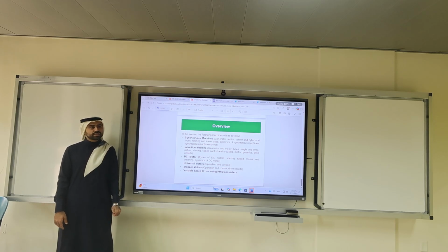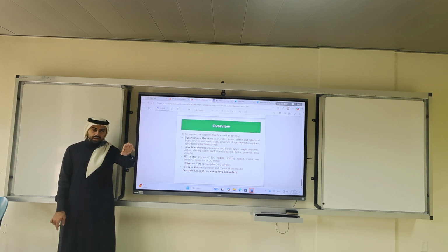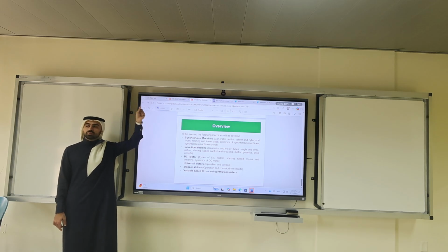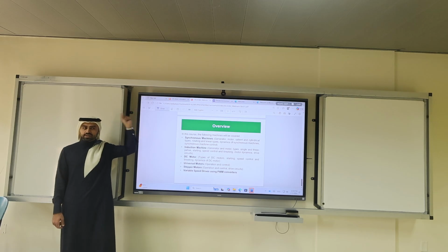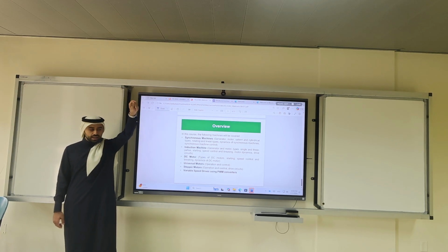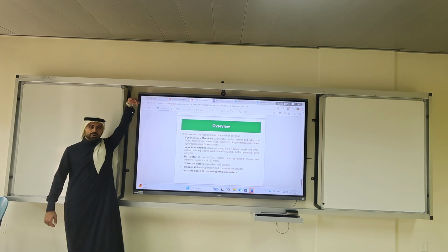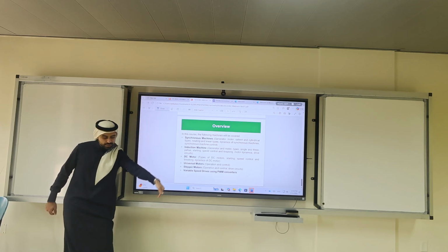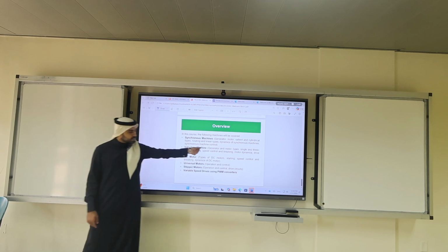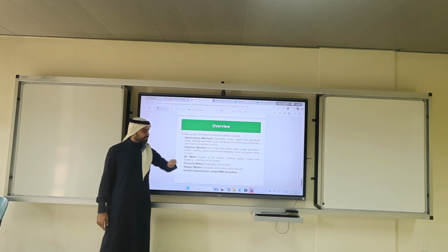Also, I remember from their discussion that the induction generator is directly connected and gives you variable frequency, which is connected to a power electronics module, so that the output from the top of the wind farm is a pure 33 kilovolt, 60 hertz sinusoidal signal. They do the work on the top before they extend the cable underground. So each wind turbine tower has cables underground, and it gives you AC signals. So induction generators are used in the wind farm, okay?